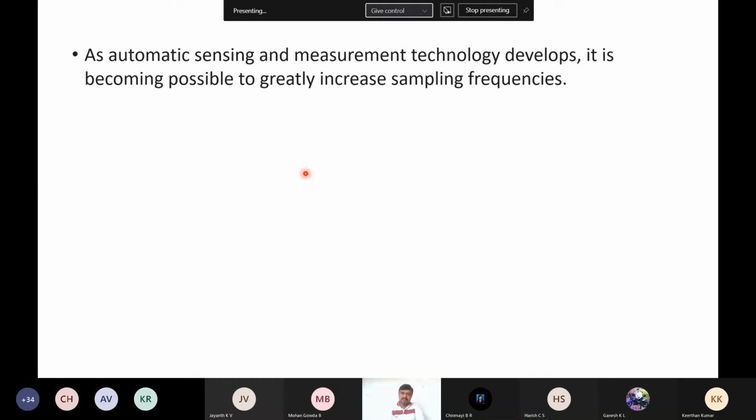Online inspection is possible because you are using sensors for measurement, and again you are using statistical process control software for getting real-time data. Based on all these things, it is possible to take more samples, or even evaluate the quality of each and every product with the help of automated inspection technologies. By automating the process of inspection, it is possible to evaluate each and every product.